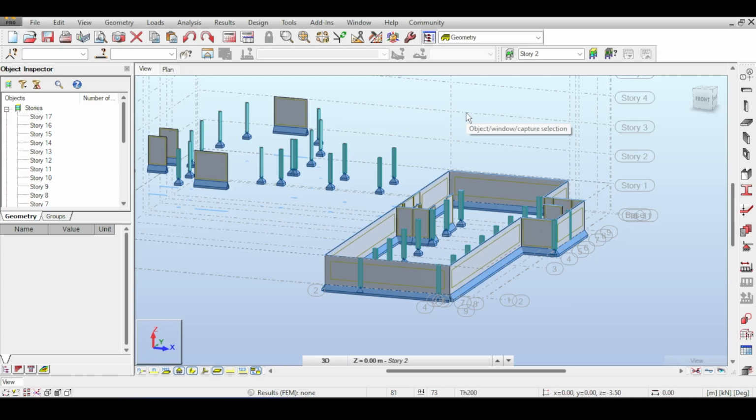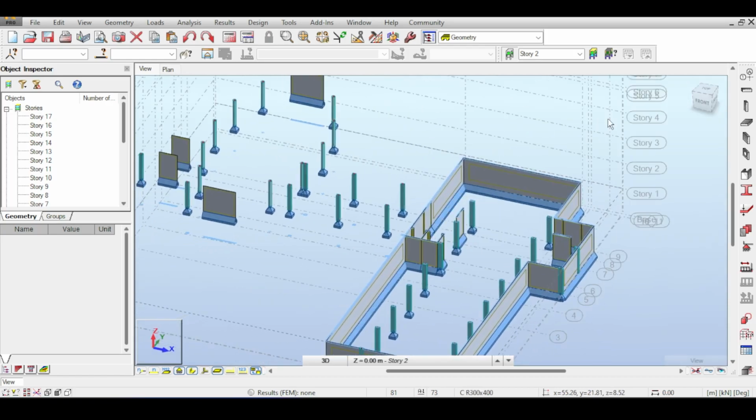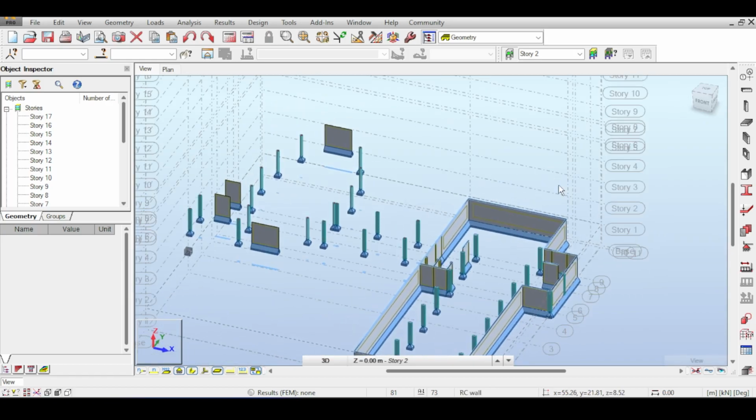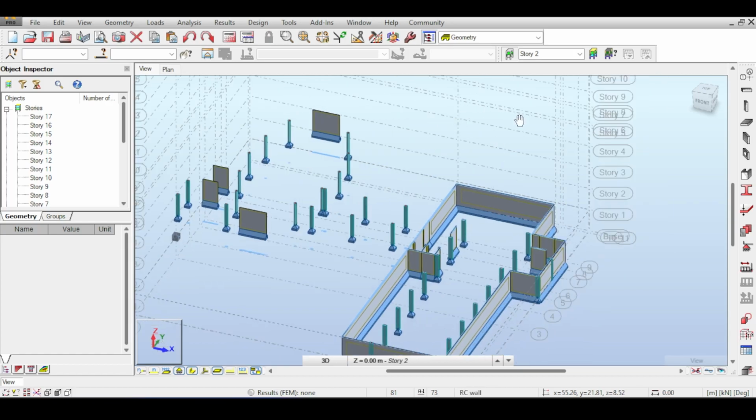You would think, okay, that's odd. The ASI code intends for those reduction factors to mimic the loss of inertia due to section cracking, and this happens during the ultimate load. Well, here I disagree. Believe it or not, the reduction of inertia and the section cracking happens even at the service load level if, and this is 90% true, the moments due to working loads exceed the cracking moments of the concrete section. Now you should check your design books to understand this.